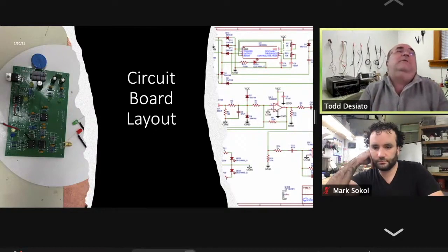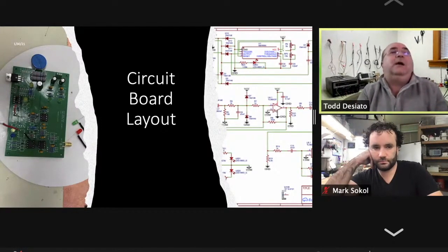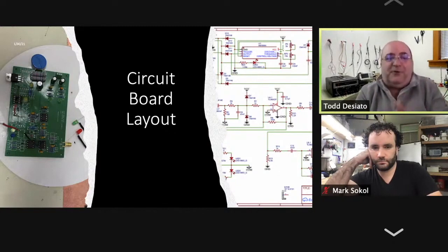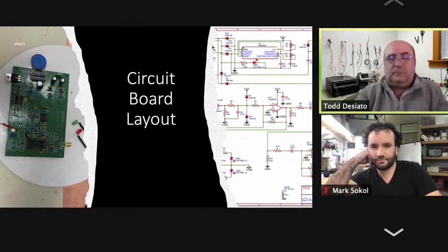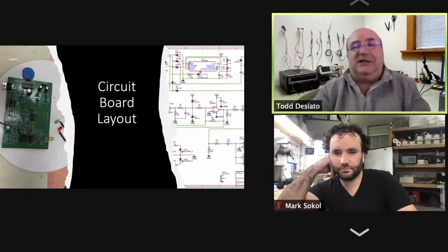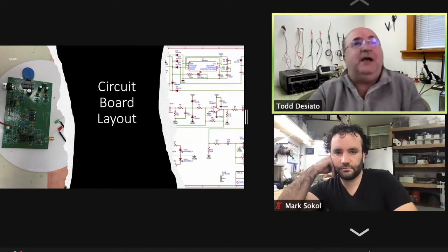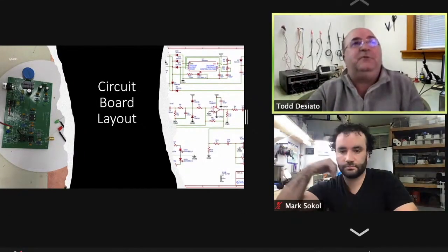So I designed this board, the boards came, I built one using 555 timers, and it would work for one frequency, but I want to try multiple materials and multiple frequencies. So I restuffed the board, and I put 4 capacitors in little sockets so I can change them out and change the value and tune it to different frequencies.